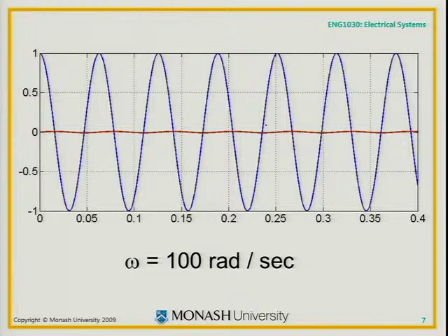It's not easy to quickly change the current through an inductor. It resists that change. And so that's what we can see happening there. In the limit, the frequency gets high enough, essentially all the voltage is used up trying to change the current through the inductor, and there's nothing dropped across the resistor.